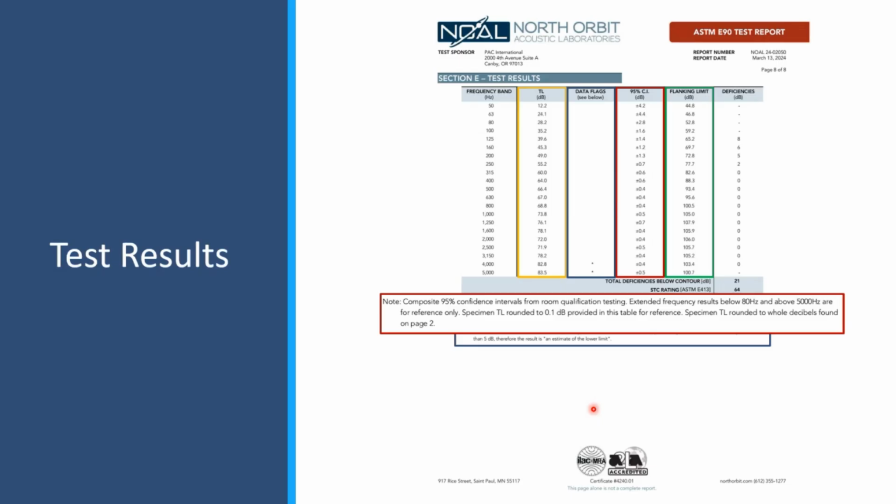The big difference in a field test is that you're in the actual building, and you haven't gone to all of this effort to isolate everything else so that you're just testing the sound coming through your partition. You have all of these other paths, and they're just normal building construction, not high-end, very specific laboratory construction. So you're going to get a lot of flanking sound through all of these other paths, right? And so you're not just measuring the sound transmission through the wall between the units, but all of these other potential paths too.